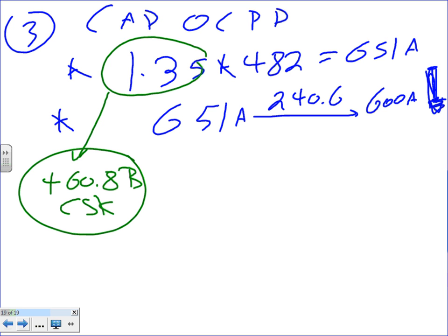My rule is, guys, to use the same multiplier for the cable, and I go down, because it says as low as practical. Well, how are we going to do it? Unless you talk to the manufacturers. If the manufacturers tell you otherwise, you just do it. For the sake of sizing, guys, that's how I do it. Use the same multiplier, 1.35 times the same current, and go down.